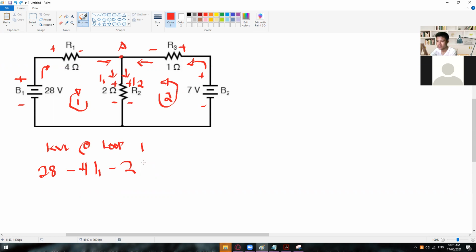Anyway, in here we have two currents dealing with this path. As you can see, we have I sub 1 and I sub 2. So that is why we're going to write I sub 1 plus I sub 2. In Kirchhoff's current law, we're going to have I1 plus I2 equal to I3, wherein I1 plus I2 will come up with another current, which is I3.